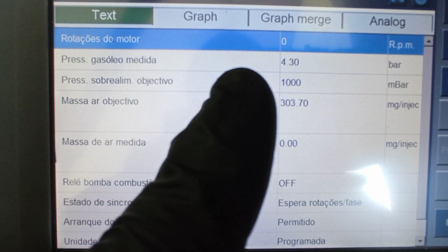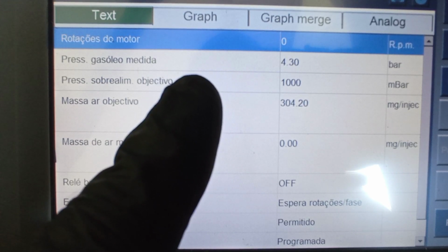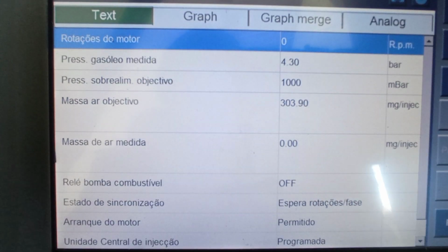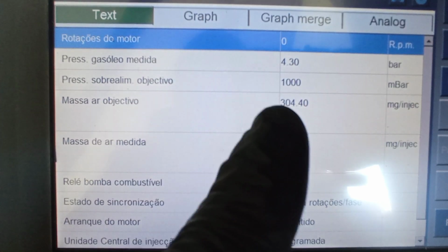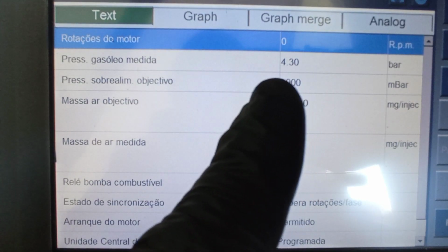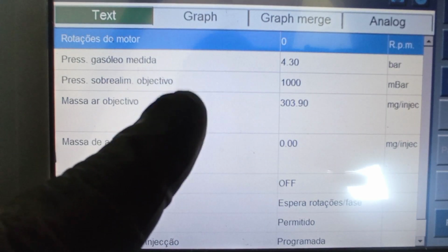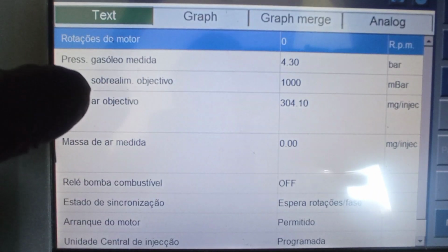If you have 4.3 bars on the system and you have a leak, you will see it very easily. Anti-return valves will not do anything for your low pressure system. On the systems that have nothing, just suction to the high pressure fuel pump, in that case, obviously, a one-way valve can solve a lot of issues.